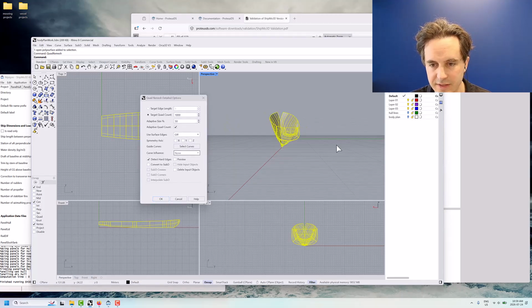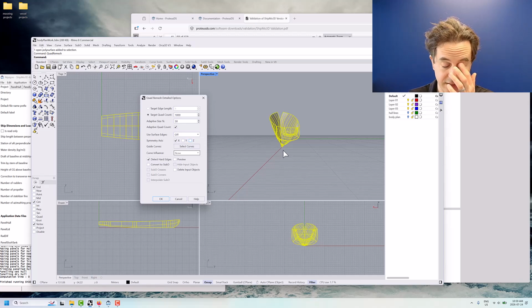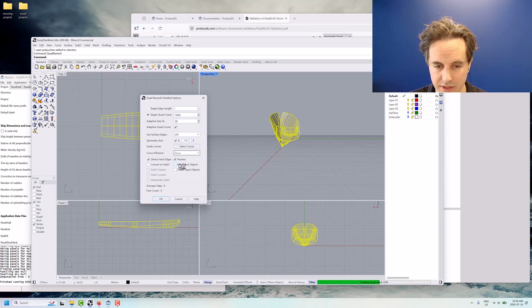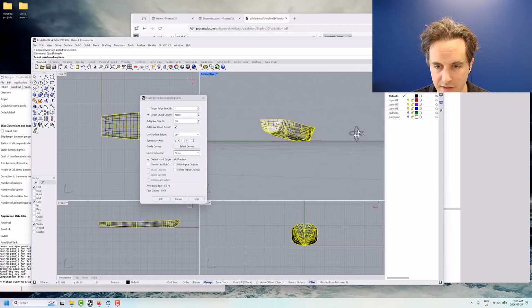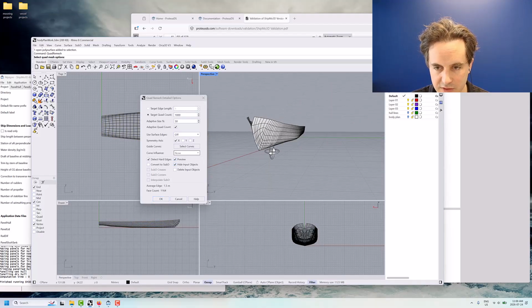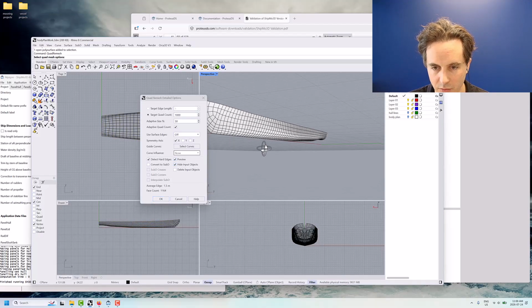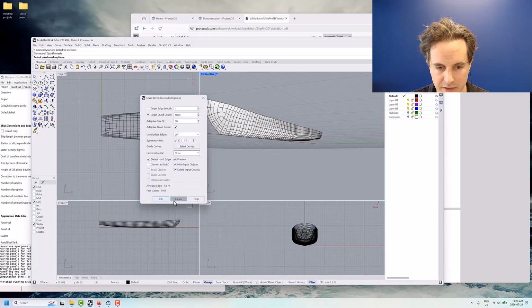The other benefit to this actually is we can pick a symmetry plane. In some cases, you have to do that for some challenging hull shapes. So we're still just going to pick 1,000. Actually, it's better, more computationally efficient this way because it's spreading 1,000 over the whole ship. And that looks pretty good, so we're going to hide.